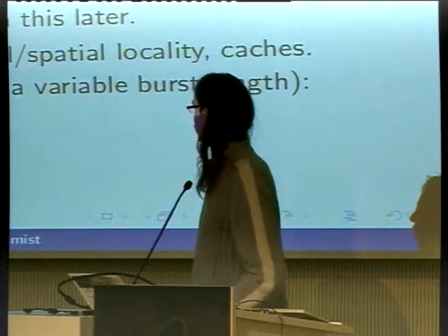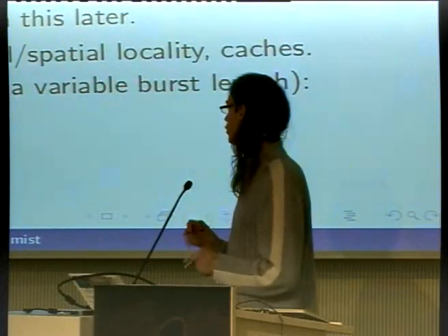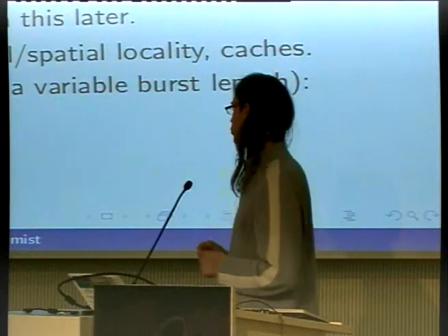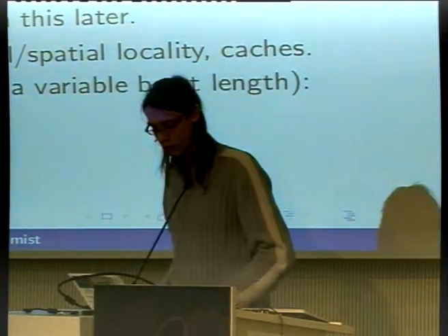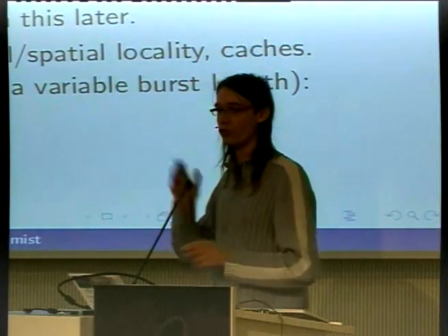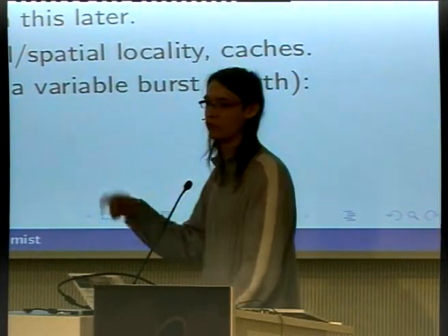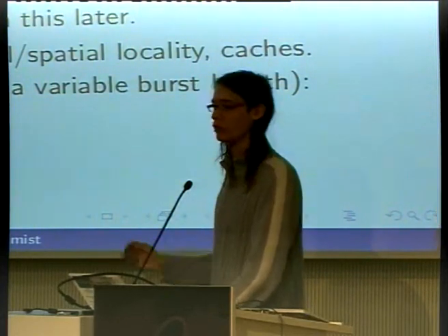And using this burst system really simplifies a lot the SDRAM controller design, the signaling of the memory bus, arbitration of the bus, and also cache controllers. It's really simple. I mean, you just have to have a counter inside your memory controller, and you request all addresses, and it turns out to work pretty well. You don't have to do any kind of speculative execution or anything complex.